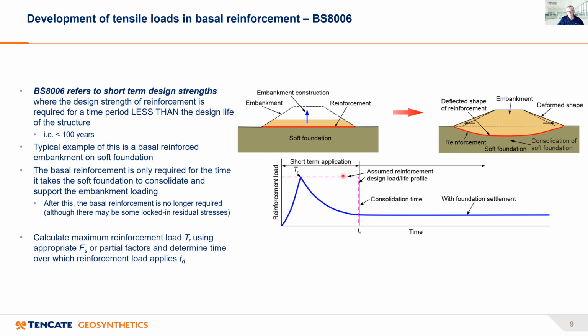That's what we determine as part of the reinforcement requirements for this embankment. And you'll notice that we only need the reinforcement until such time as the soft foundation soil consolidates. That may be 5, 10, 15 years, whereas the embankment itself is designed to last for 100 or 120 years.